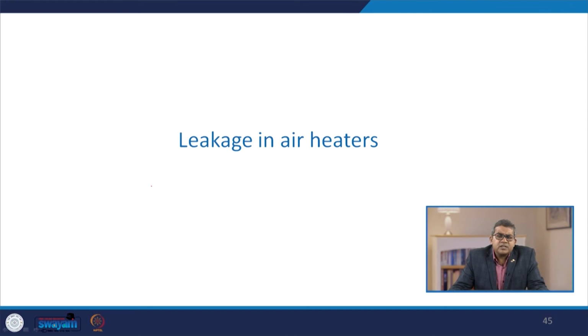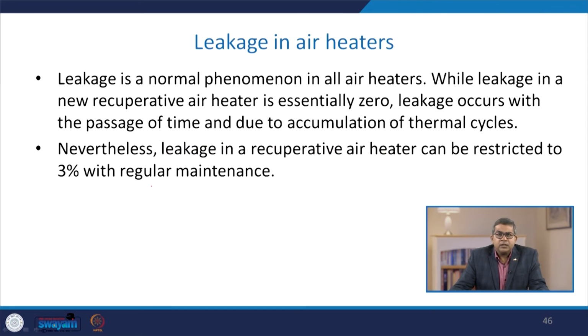Sometimes you may experience leakage in air heaters. Now, leakage is a very common or normal phenomenon in all air heaters, while leakage in a new recuperative air heater is essentially zero. Leakage occurs with the passage of time and due to accumulation of various thermal cycles.